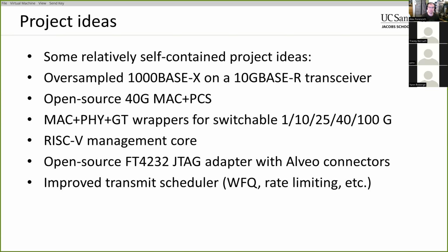And the other thing is that if it's all running the same kind of base firmware, it makes it a lot easier to add new features to it, because the OS side interface code you could probably just use the same thing. If you have to make an improvement to that, you just need to rebuild all the code for all the individual boards. You don't need to individually update each piece of firmware, especially if you're running on different cores.